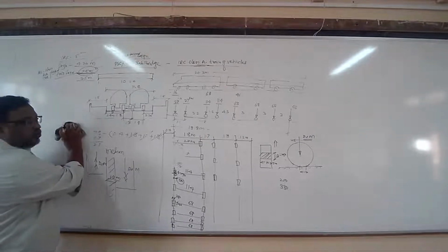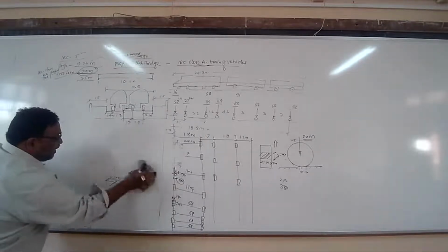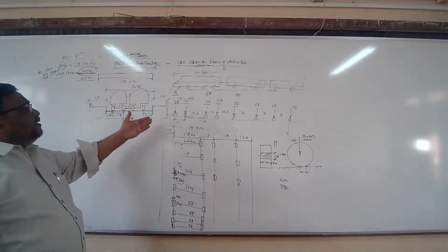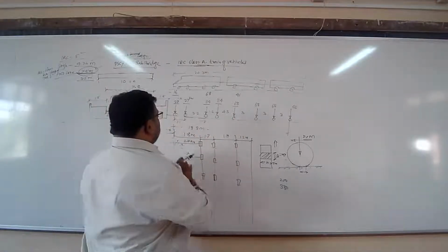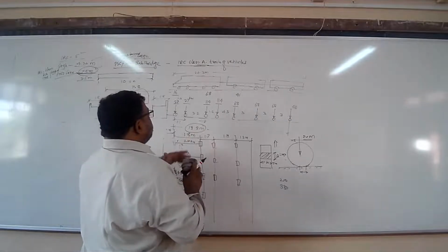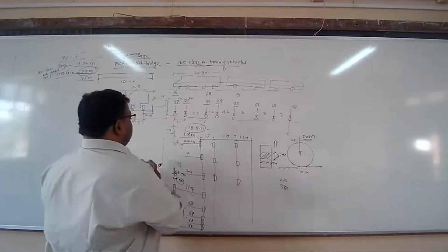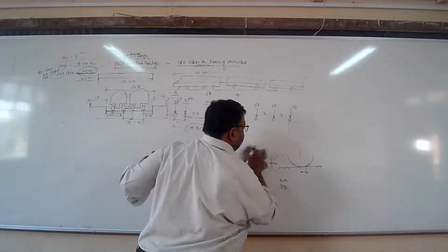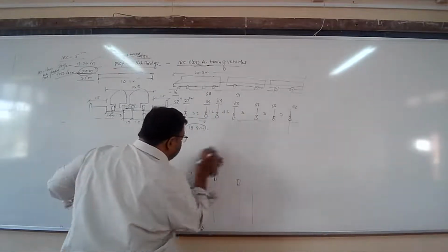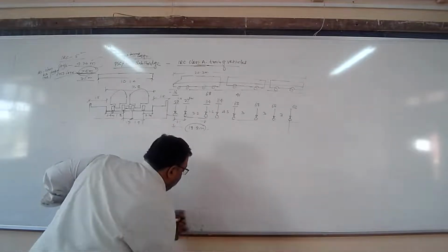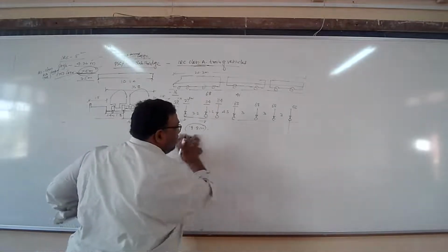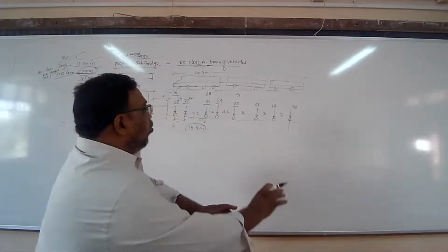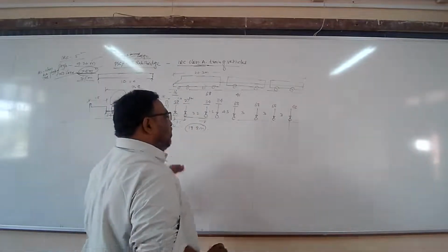अच्छा, what to do? अभी हमने along के लिए क्या करना चाहिए? Vehicle ये कितना है? 10.4 मीटर. अगर मैं एक्सल टू एक्सल कंसीडर करता हूँ तो दिस इज 18.8 मीटर. तो इसमें से कौन से व्हील मैंने कंसीडर करना चाहिए? Which of the wheels must be acting on the bridge? उसके लिए क्या किया था हमने? We had considered the wheels passing the center line one by one. Do you remember that guideline?